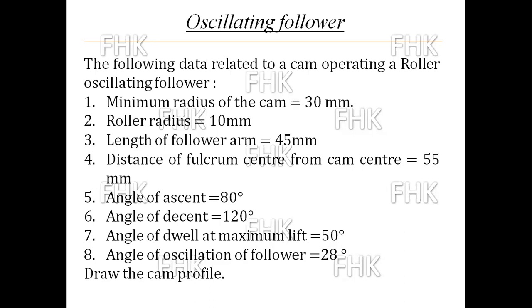Angle of ascent is 80 degrees. Angle of descent is 120 degrees. Angle of dwell at maximum lift is 50 degrees. And last, angle of oscillation of follower is 28 degrees. We have to draw the cam profile for the given data.